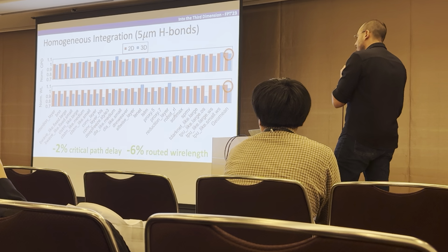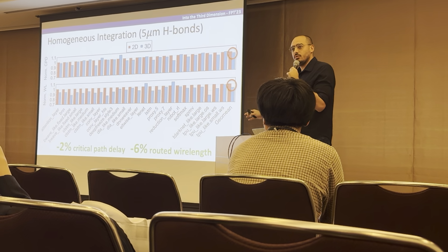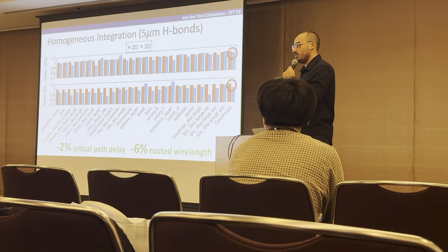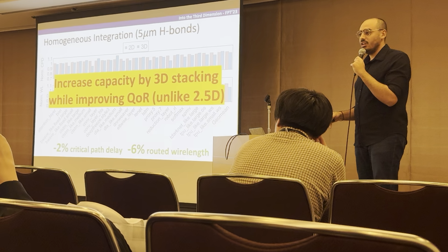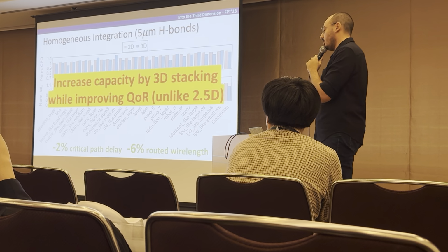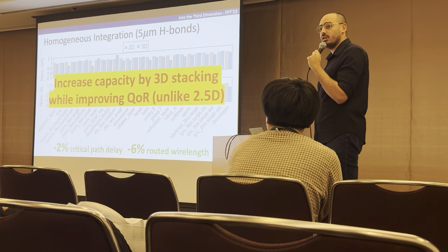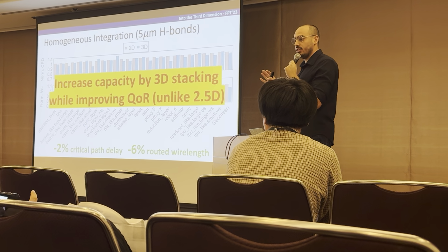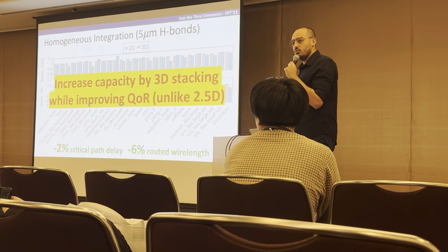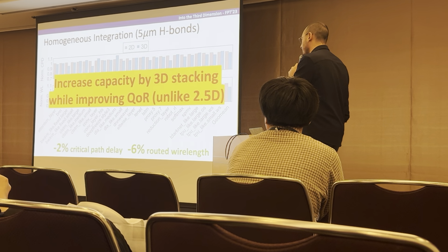Those are already by themselves decent gains in terms of quality of results, but this is really not the reason why you would go and build a 3D FPGA. The key takeaway here is that 3D stacking can help us significantly increase the logic capacity of the device while improving the quality of results, which is not the case of what we have now in 2.5D integration.